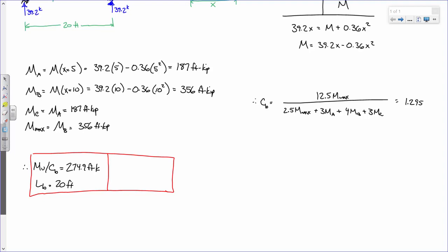All right. So remember, on the bottom, look for 20 feet, and on the vertical axis, you're looking for about 275 in the blue numbers. And then you find that point, look up to the right, find the first solid curve that you can find. Everybody got an answer for me?